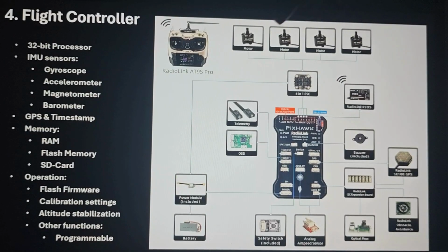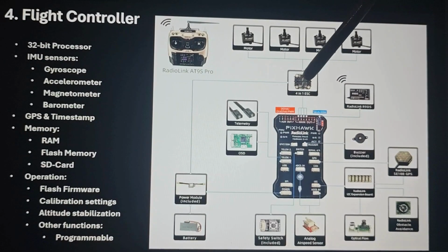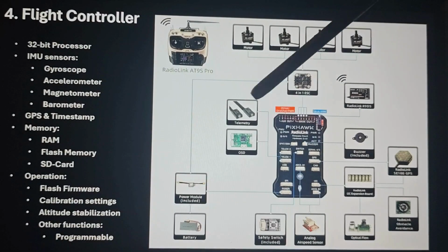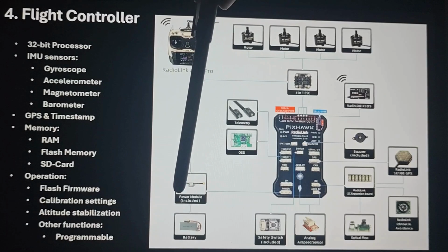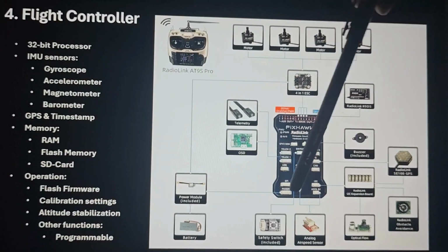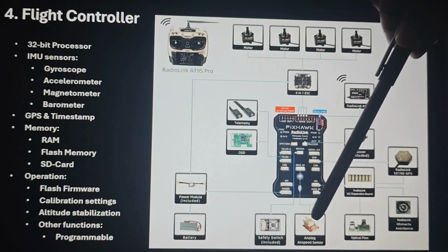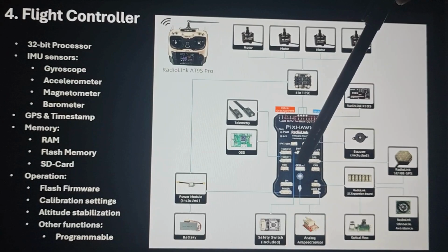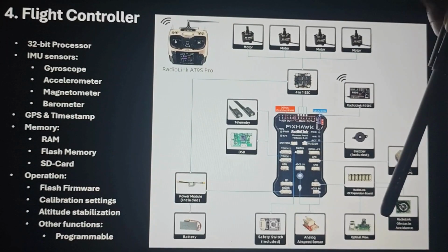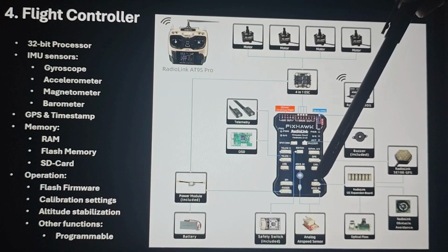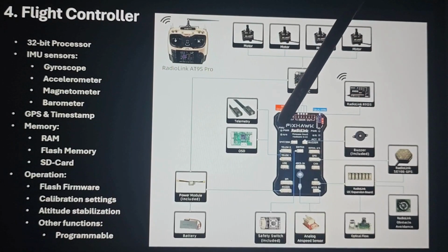These 4 are the motors. Through the electronic speed controller, they are connected to the flight controller, and this flight controller is powered by this battery through the power distribution board here. And also various sensors are connected. For example, analog sensors, for example a wind sensing sensor, which is connected to the ADC part of it, whereas digital sensors such as cameras are connected through the interface called I2C to the flight controller.